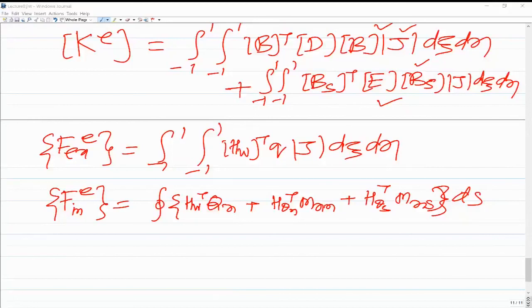Sir, in the isoparametric element we are considering four shape functions, but for the similar case, for the classical plate bending element, we are considering 12 shape functions. Here, although the degrees of freedom are the same, w, theta x and theta y, so 3 degrees of freedom, there also we have 3 degrees of freedom: w, del w by del x and del w by del y.